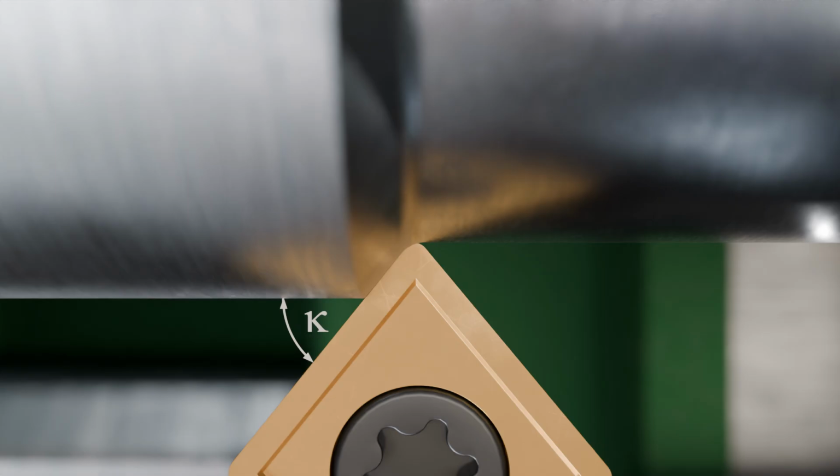tool and the workpiece. By decomposing the forces at a given approach angle, it quickly becomes clear that the normal force of the cutting edge can be resolved into an axial component called FF and a radial component called FP. The force in the axial direction corresponds to the force with which the turning tool must be moved during longitudinal turning in the direction of the feed to machine the material. This axial force is therefore called the feed force FF.